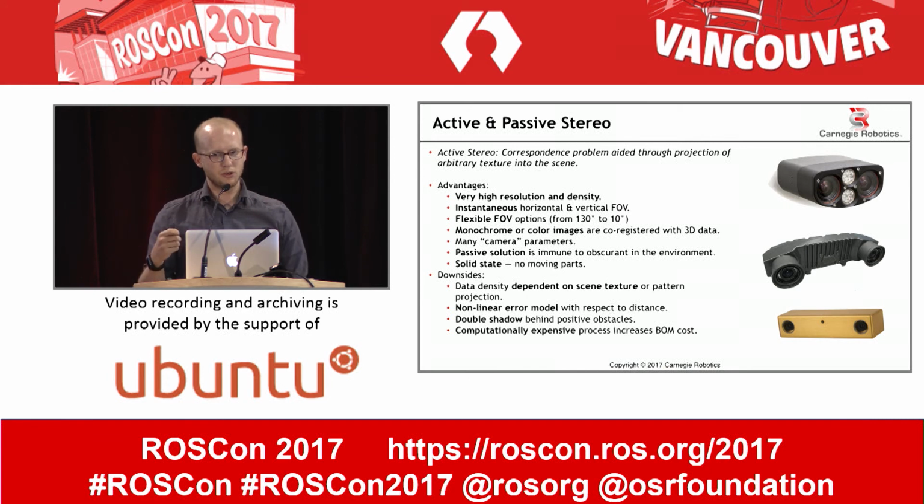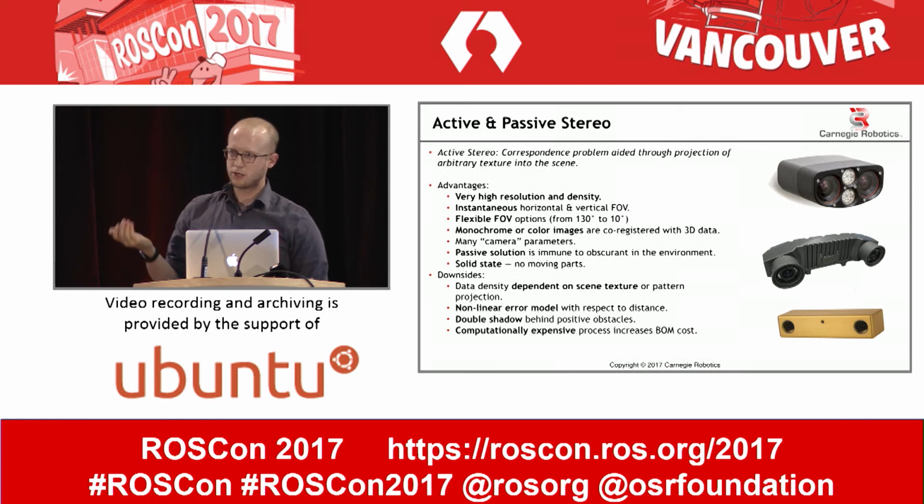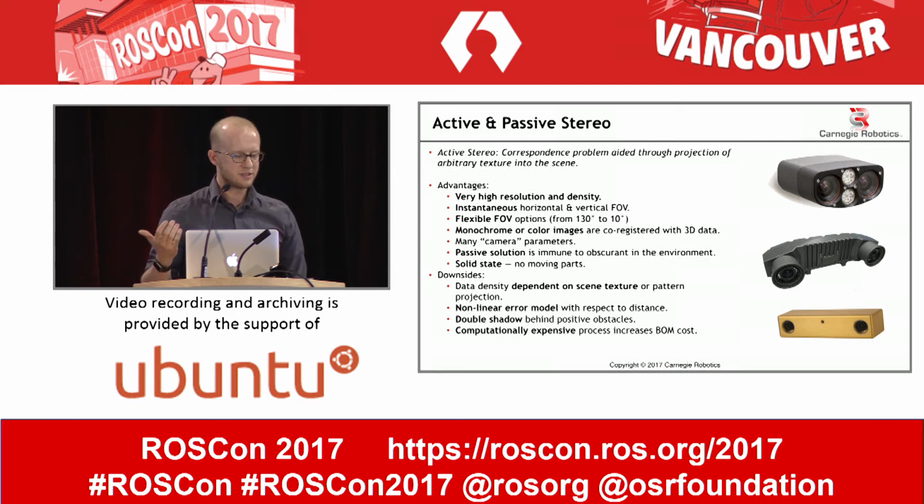But it's a very computationally expensive process to do the stereo matching, this correspondence problem between the two cameras. So if you're doing stereo processing on a general purpose computer, you're limited in resolution or frame rate or the disparity search range. That's part of why we embedded the stereo matching process inside of an FPGA in our cameras, the top two cameras here. That reduces the power required to do the stereo matching process, as well as reduce the latency to get the 3D data.